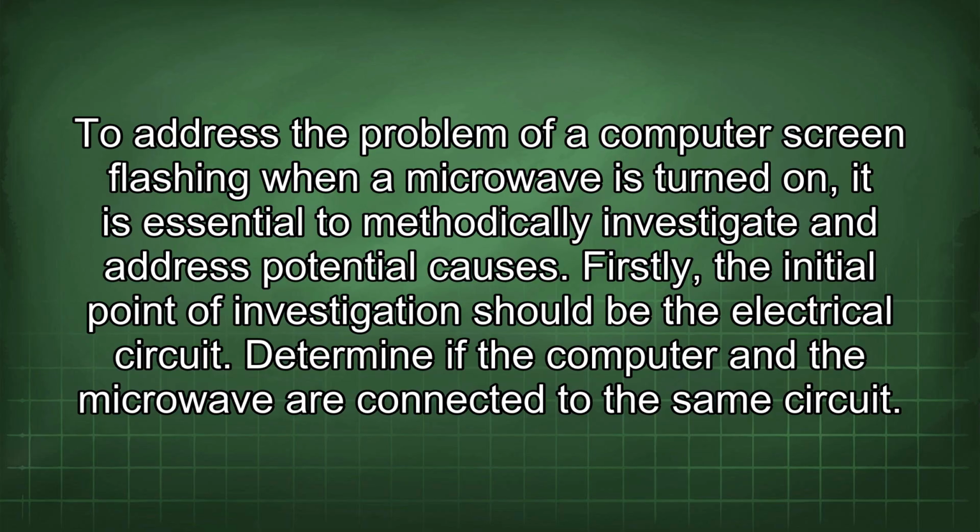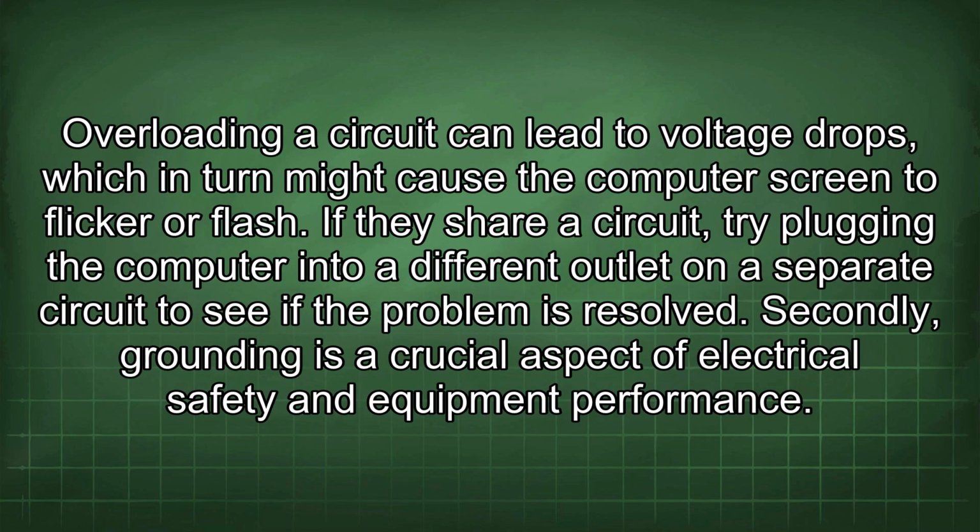To address the problem of a computer screen flashing when a microwave is turned on, it is essential to methodically investigate and address potential causes. Firstly, the initial point of investigation should be the electrical circuit. Determine if the computer and the microwave are connected to the same circuit. Overloading a circuit can lead to voltage drops, which in turn might cause the computer screen to flicker or flash. If they share a circuit, try plugging the computer into a different outlet on a separate circuit to see if